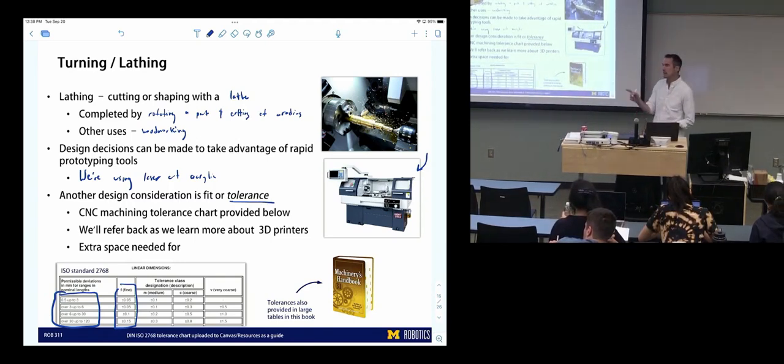Yeah. So what sort of fit is this chart supposed to provide? Would it be like an interference fit or a press fit or something else? This uses a class of fits that's called maybe a locational clearance. Within tolerancing, there are these different class types. For example, interference is one. That means that the tolerances of the male and female part will be overlapping, meaning those parts could physically interfere. If anything interferes, it will not assemble.